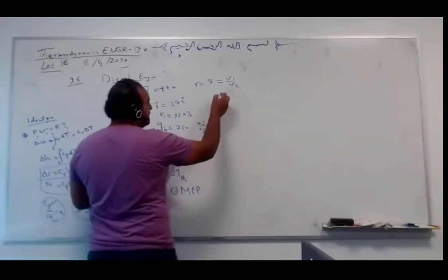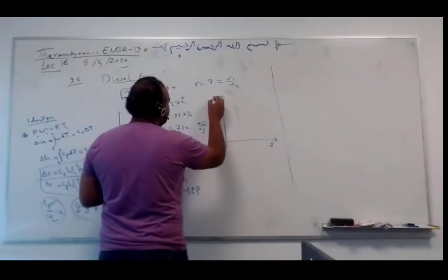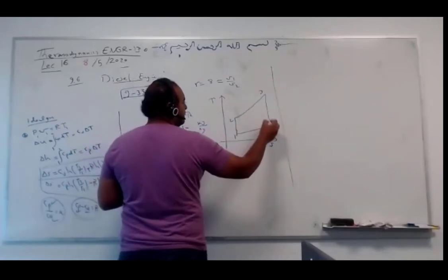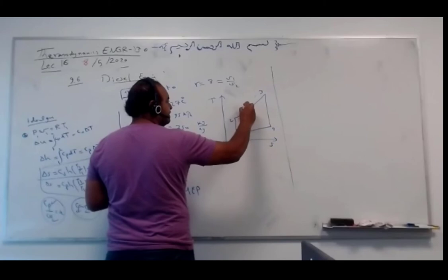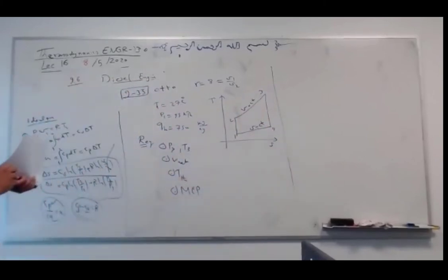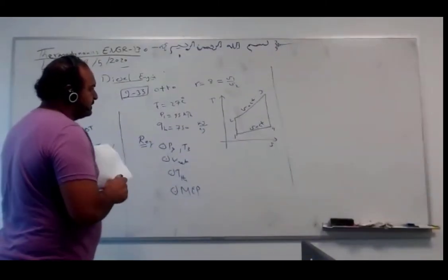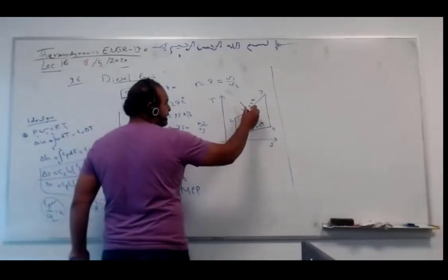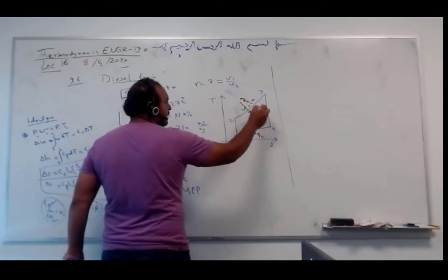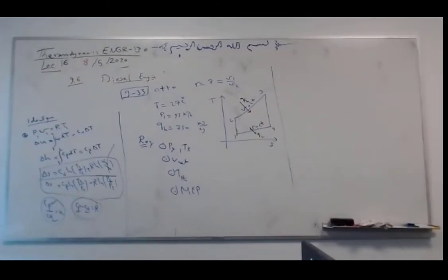So let's plot it for you. This is the solution. Plot the TS diagram. It's 1, 2, so 1, 2, 3, 4. Constant volume. 1 to 2, isentropic compression. 2 to 3, heat addition. TS diagram, I like the TS diagram. So this is not given. This is the heat Q high. This is Q low. That's small. And this minus this is the work net. Okay, guys?